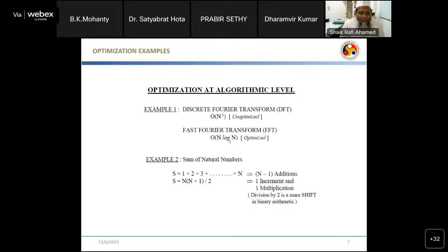As a research problem, you can take some system. There are a lot of algorithms involving a lot of multiplications. In fact, these techniques you can apply anywhere. If there is some algorithm where we have a lot of multiplications and you want to implement the VLSI architecture, then you can replace all the multipliers using DA based blocks and you can reduce the complexity. For the experimental purpose, you can implement a simple multiplier also using DA.